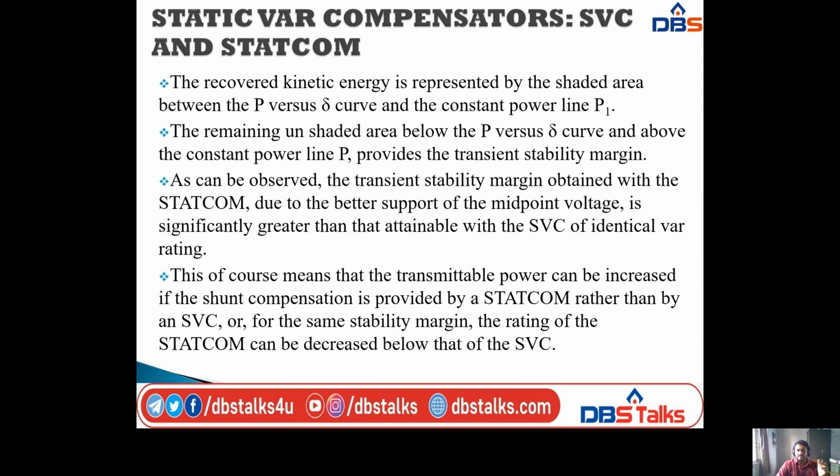As can be observed from the diagram, the transient stability margin obtained with the STATCOM, due to better support of the midpoint voltage, is significantly greater than that attainable with the SVC. That is, the transient stability margin obtained is higher compared to an SVC of identical VAR rating.